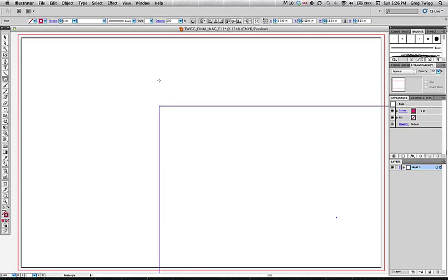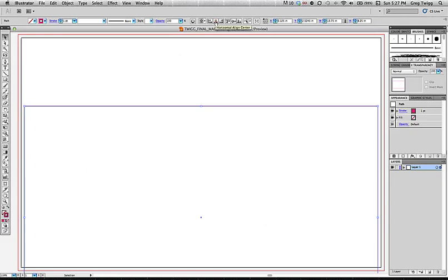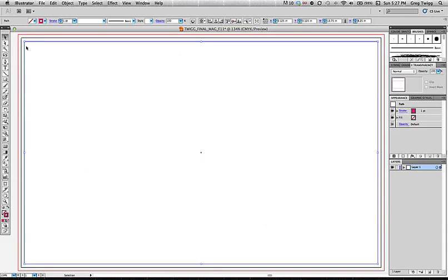And as soon as I hit OK, then it gives me this box, and depending on where I clicked, it's just going to put it somewhere where it shouldn't be. And this is when the align tool becomes super important. So I'll use my selection tool just to make sure that we all see it. My align setting is set to artboard. I am going to center horizontal, and I'm going to center vertical. And that ends up making sure that it's perfectly placed within the boundaries of my artboard, and it's going to be equally spaced on the left, the right, the top, and the bottom.